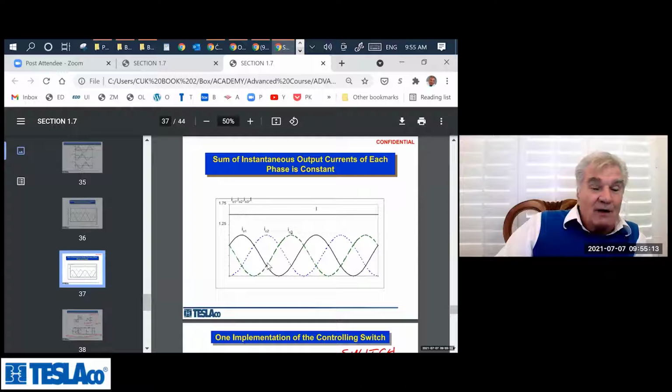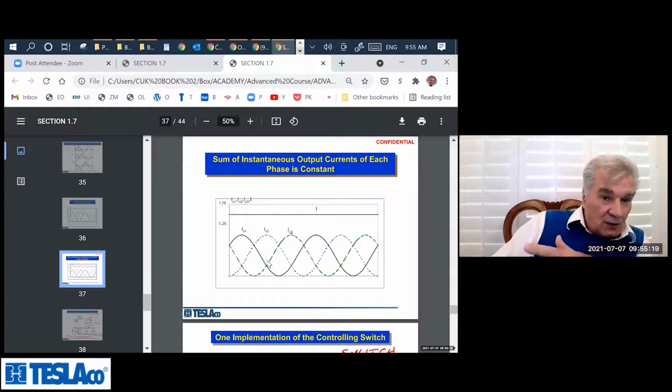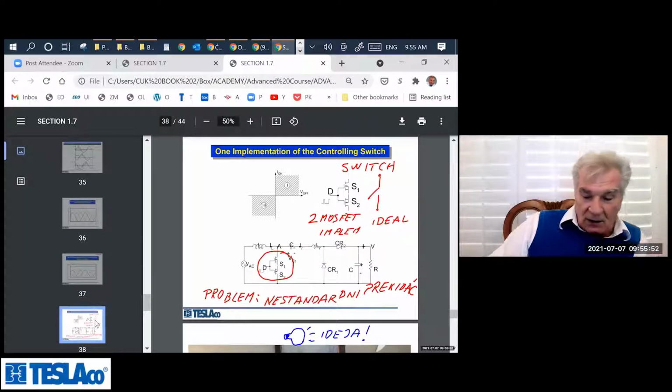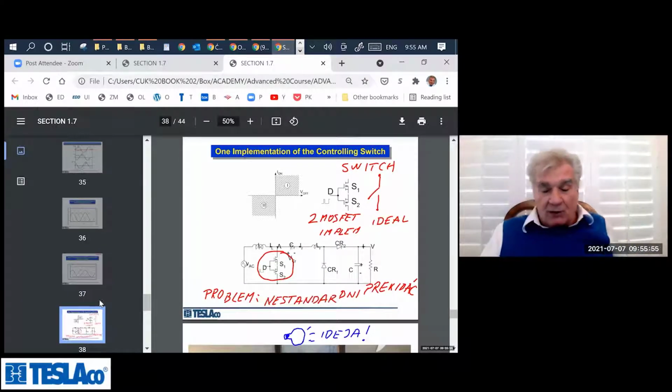Now if I have three phase converters operating from a three phase line into a single rectified load, the three phase currents cancel. Why is that important? I don't need the 60 hertz filter, because single phase requires a 60 hertz filter to filter out the ripple. But now the three phase 60 hertz currents cancel, and all I need is a switching frequency ripple capacitor on the output. So there is no need of a big capacitor either. That was a question that was mentioned before.